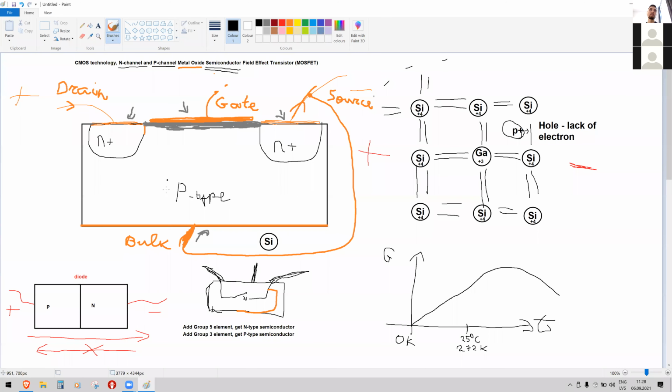So P type material needs to be turned N to start conducting from N pockets through N region to the second pocket. So this will be called N channel. What I have drawn here is N channel. P substrate, and then inside this P you can make a region N and start conducting, or switch it off, then it becomes back P and doesn't conduct. Transistors by default don't conduct, only if you apply voltage then they start to conduct.